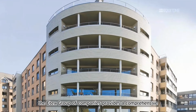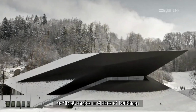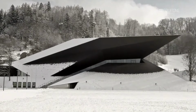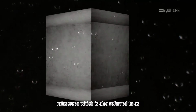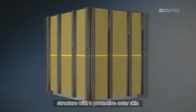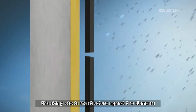The ETEX group of companies provides a comprehensive range of facade claddings to fit all shapes and sizes of buildings. These claddings are used as a rain screen. Rain screen, which is also referred to as a ventilated facade, is a kind of two-stage construction: an inner structure with a protective outer skin. This skin protects the structure against the elements.